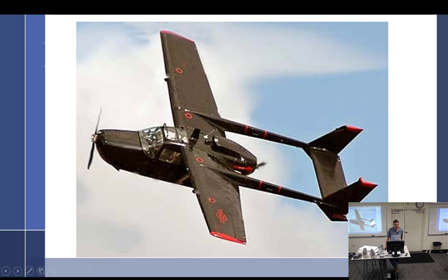The problem with this particular aircraft is, first of all, they wanted to make a centerline thrust. So if you have a twin engine rating in this aircraft, it's inline thrust only. You're not allowed to fly a twin with engines out on the wings because you're not trained for that. So you have inline thrust. And one of the problems with this aircraft, the way I understand it, is it will climb poorly with one engine out, at about 200 feet per minute, which is not much at all. Again, I don't know for a fact. I've never piloted one of these, but I hear its climb rate is not very good with single engine performance, especially with the rear one, or one of them not feathered.